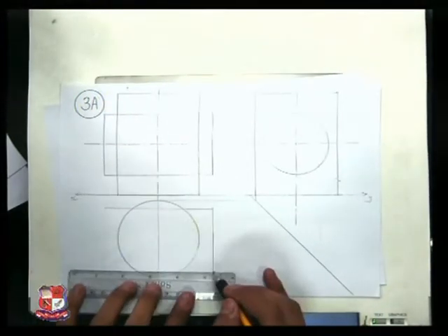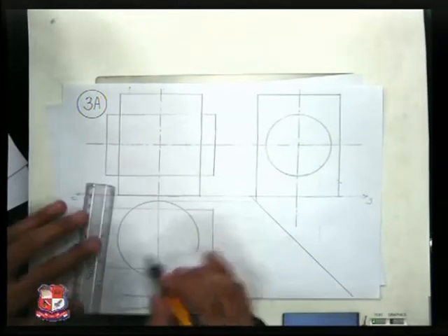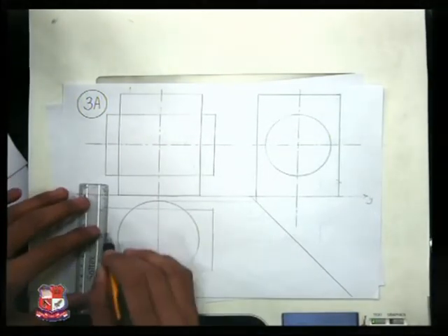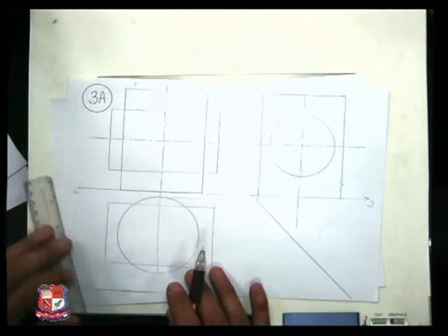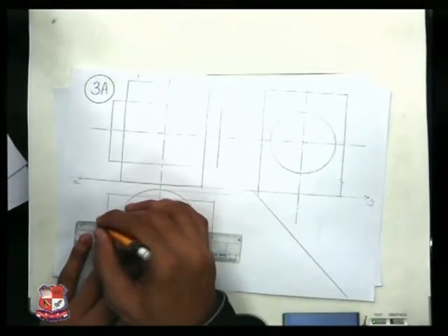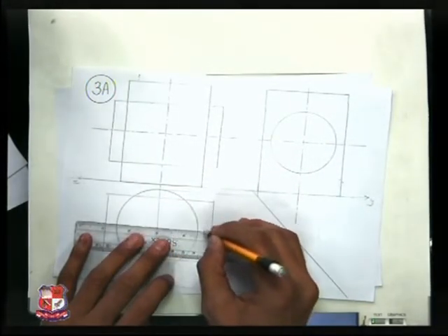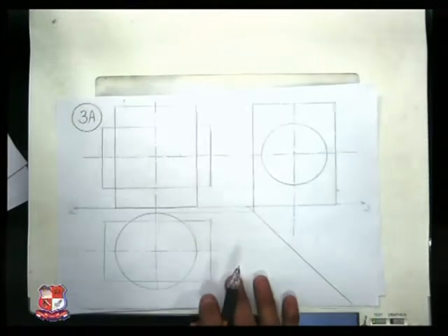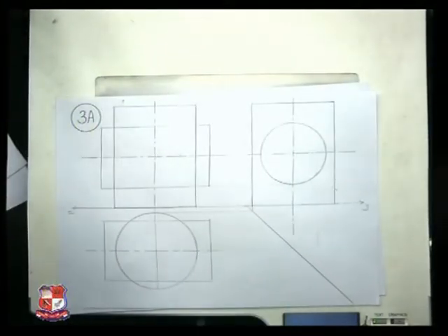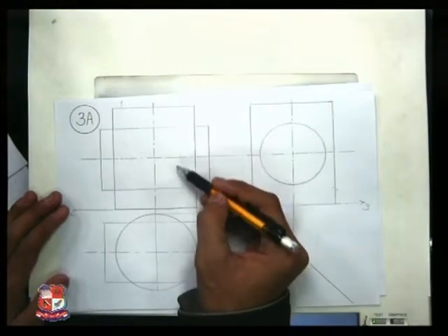Both will be the same, having a rectangle of width equal to 100 millimeter and height equal to 60 millimeter, that is the diameter of that penetrating cylinder. And this is the axis of that cylinder, that is the horizontal cylinder, or say penetrating cylinder. So this is the case which we have drawn. Now we have to find out the curve of intersection, which is over here.